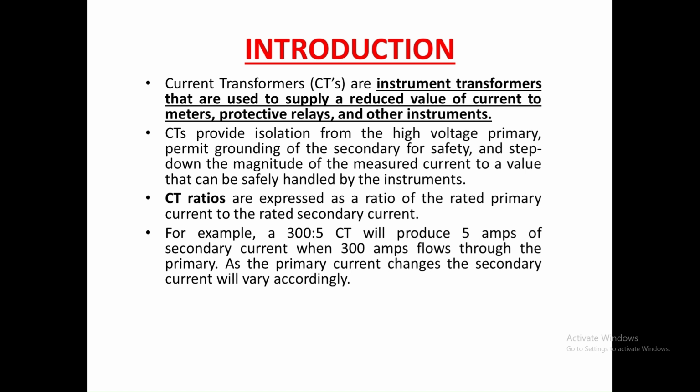We need to step down the value of the current through CT, and that can be helpful for other aspects also. The CTs provide isolation from the high voltage primary and permit grounding of the secondary for safety, and step down the magnitude of the measured current.